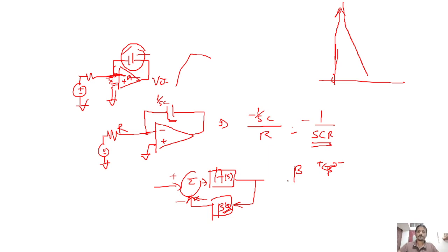Okay. That's what I think the pole zero concept is all about, right? See, I have poles here, so if I work at a particular frequency which won't reach these poles, then it is actually stable. If it is reaching a particular pole which is on the right side of the j omega axis, definitely it won't be stable. So the feedback action itself changes, right?